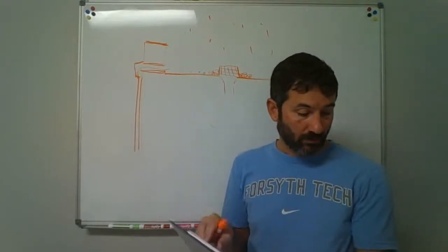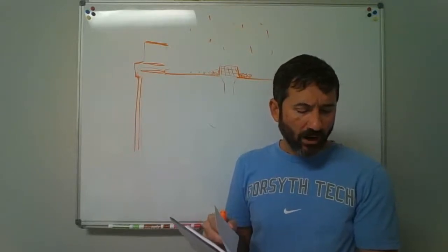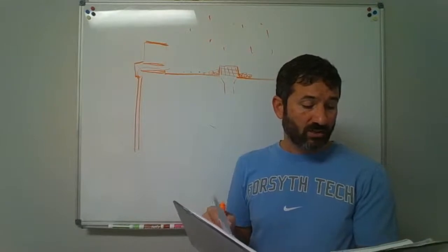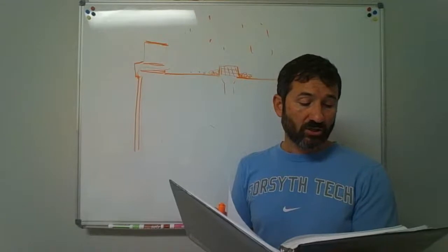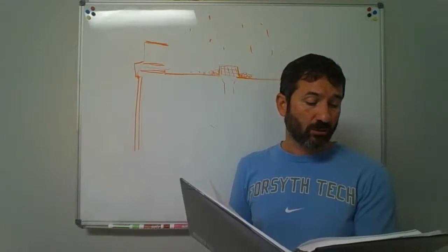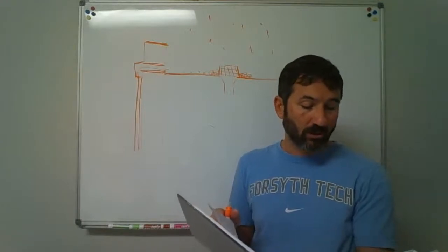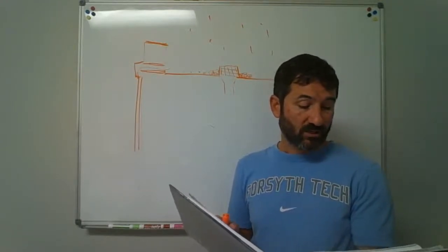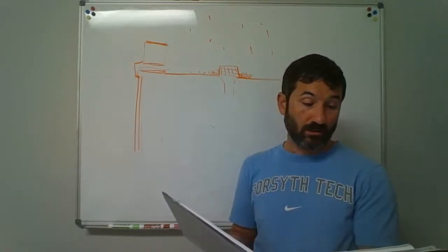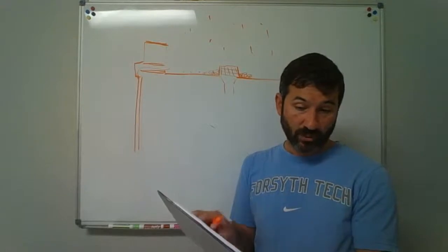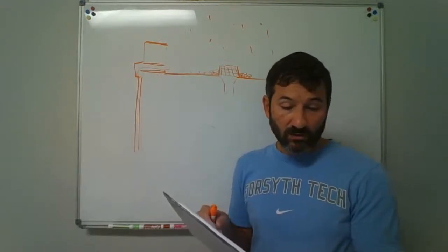Okay. Separate systems required. The secondary roof drain system shall have the end point of discharge separate from the primary system. Discharge shall be above grade in a location that would normally be observed by the building occupants or maintenance personnel. You want to know if that's clogged or not. And then they give sizing of the secondary drains. Actually, that's what we looked at for there. Let's see, what else am I going to have you look at?